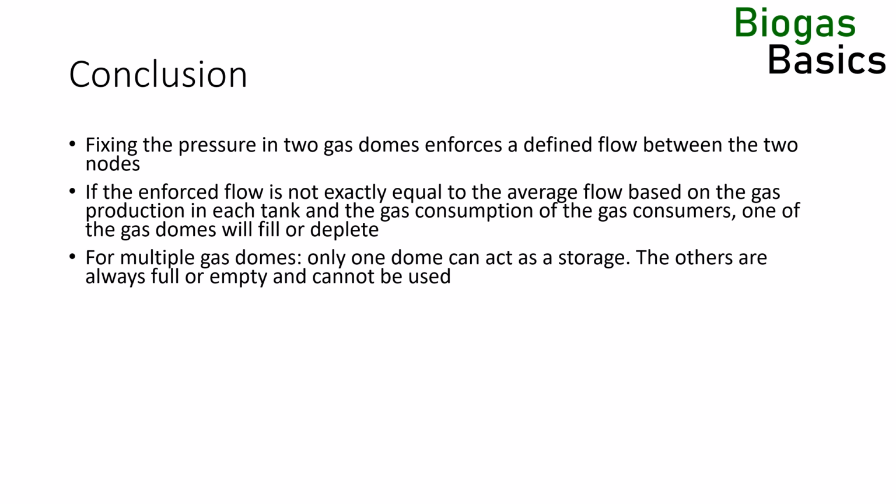For multiple gas domes, only one dome can act as a storage. The others are always full or empty and cannot be used. In the best case scenario, and after careful setup, it might be possible to use some gas domes sequentially, but most of the time, the gas dome volume cannot be used fully as storage space.